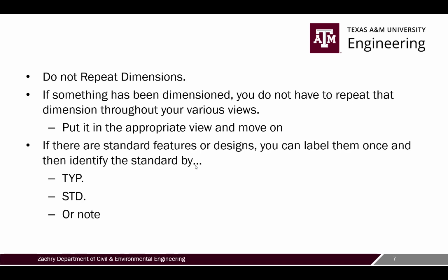So one of the key things, if you've dimensioned it once, don't repeat it. So if you've dimensioned it in a certain view, don't repeat that dimension in all your various views unless there is a reason for it, because that's when you start becoming unclear. It is the tendency of people that are in the profession that if they see a dimension in one view and then see a dimension in another one, that they're not actually going to be expecting that, because they know you're not supposed to repeat dimensions. So if they see that second one, their thought process is, what are you dimensioning? So you want to put it in the appropriate view and move on.